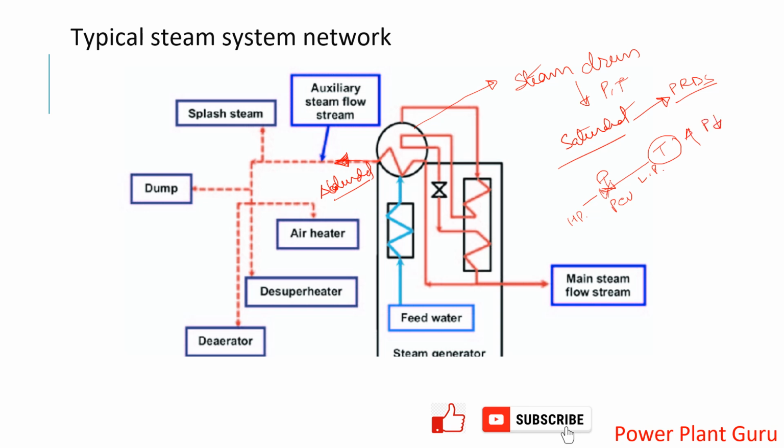So the saturated steam temperature may be suitable for whatever pressure you are going to let the steam down to, for use in heating, for example a steam coil air preheater, or maybe it is going into the deaerator. That is where saturated steam is also used sometimes, so that once you lower the steam pressure, the temperature is good and you can utilize that steam.